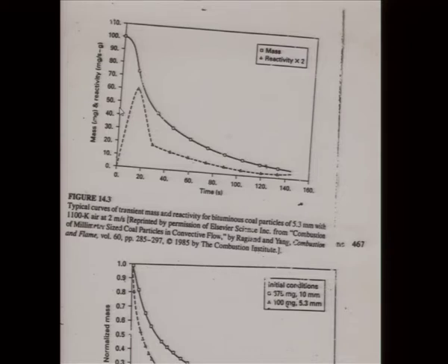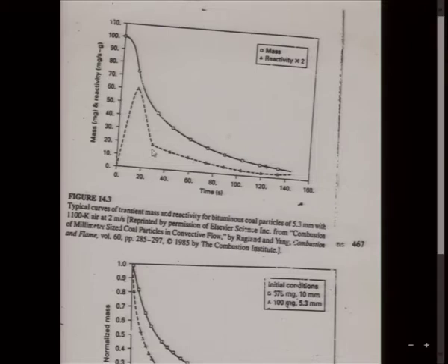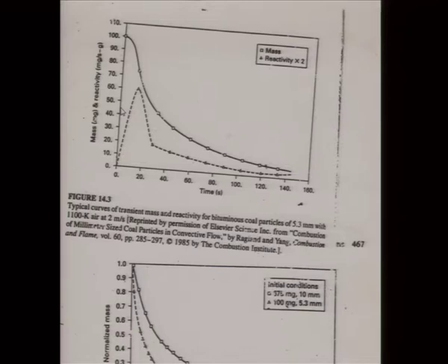So that tells you that the volatile matter in the coal is much lower. Again, I forgot the percentage, but it's much lower than 55. But here it has lost 55% of the mass, isn't it? How do I know? I am going up from this point, and I arrive here roughly, which is 45 mg, correct? So that means 55 mg has been lost, that is 55% of the mass has been lost because of pyrolysis, devolatilization. But proximate analysis predicted much less.